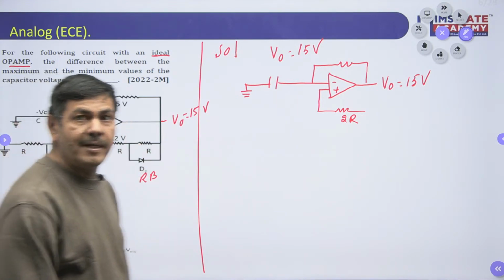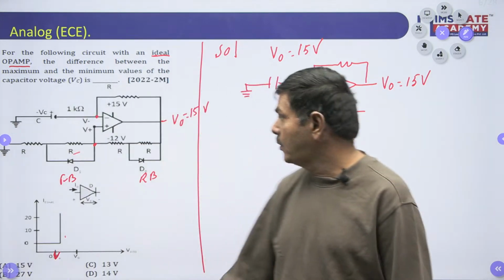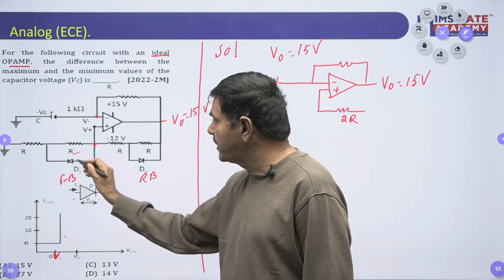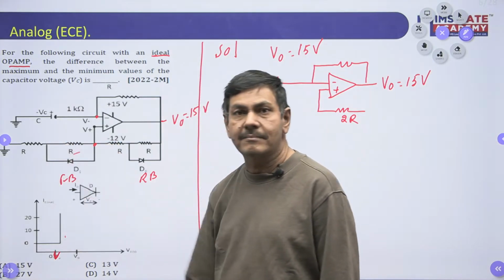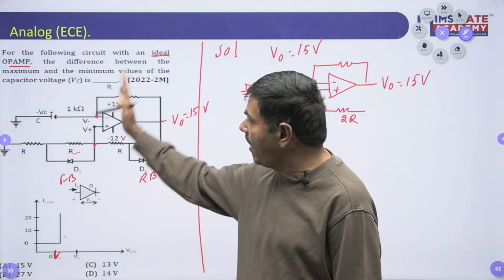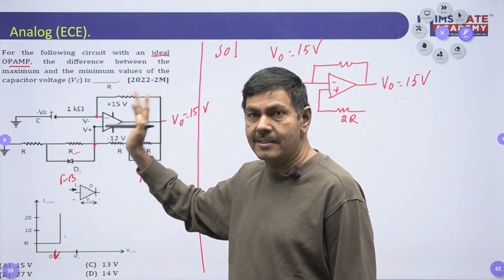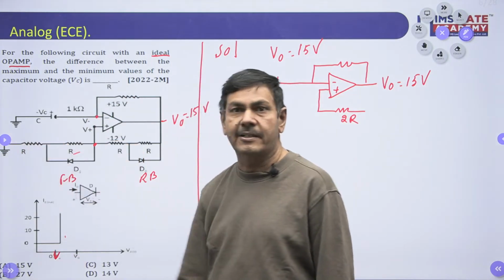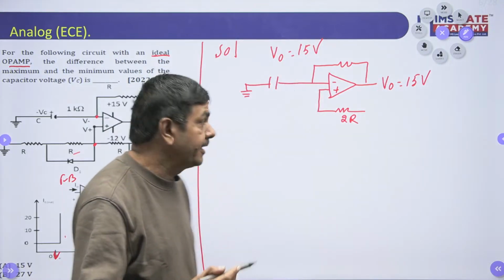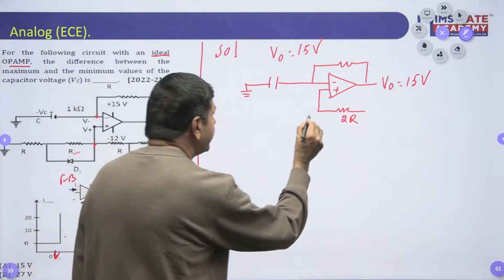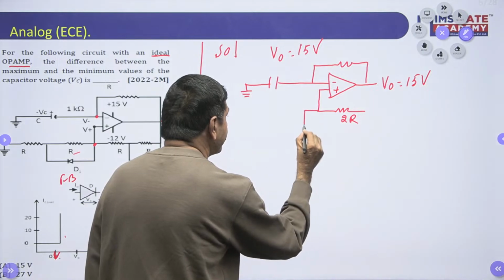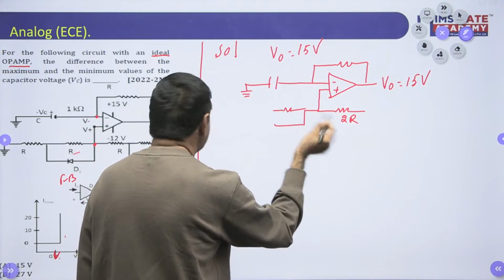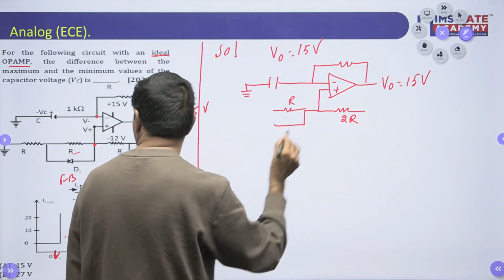This D1 is forward biased. Catch my point. The diode D1 is forward biased. This is short circuited. If it is short circuited now, no current is going to pass across this R. At that time, even if you remove that R, it doesn't cause a problem. The diode is shorted and connected to the resistance R directly here now. I'm repeating: this can be drawn in this way. This is shorted. The resistance is not going to have any importance now. That is unnecessary.